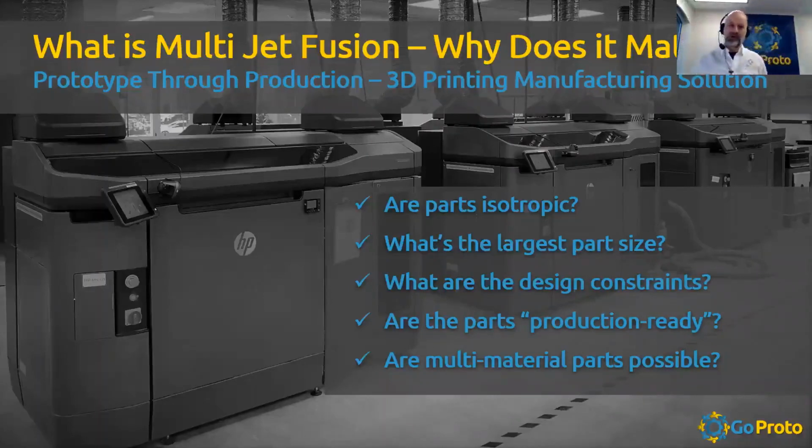There certainly are design constraints, and that's important to know, and we can talk with you about your individual products to go through it. But there are things like minimum wall thickness. You don't want to get features or walls that are less than about a millimeter. You start to get below a millimeter or 40 thousandths, and things start to become wishy-washy. Sometimes they'll work great, sometimes they won't. Depends on your particular design. Making real thick parts can create some thermal load on the printer, so you can get things like elephant skin, it's called, where you get some surface imperfections and sometimes hard to hold tolerances and so on. So yes, there are definitely things to consider.